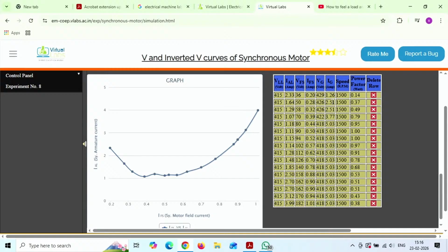Okay, this is IA, and this is the unity power factor. What is this region and what is this region? Correct. Thereby we should derive this. An overexcited synchronous motor is in the leading power factor region. Overexcited is leading, underexcited is lagging for a synchronous motor. Correct. And it is reversed for a generator.